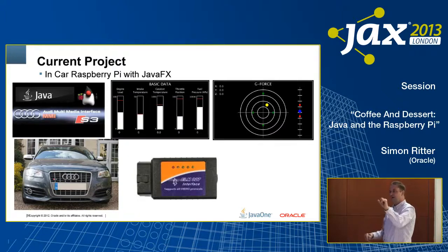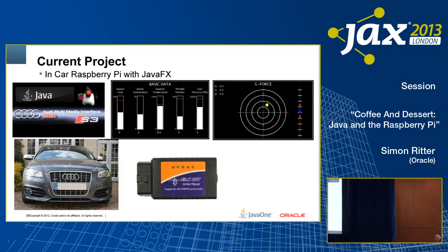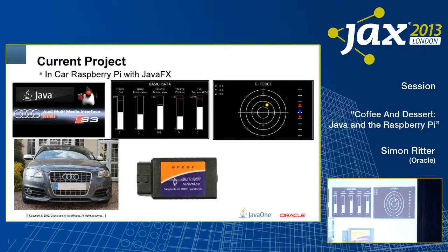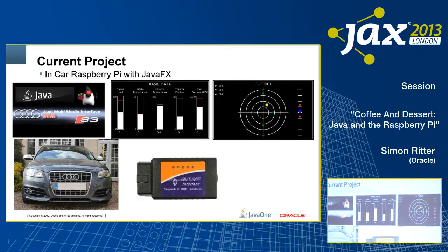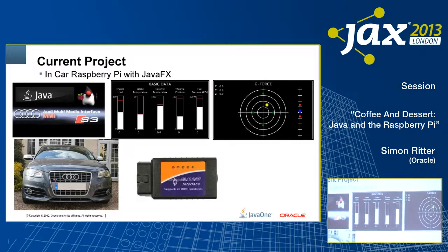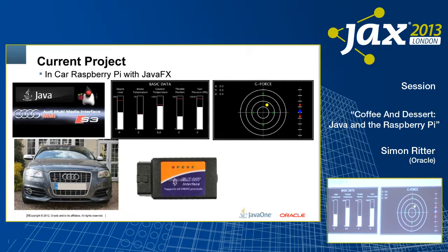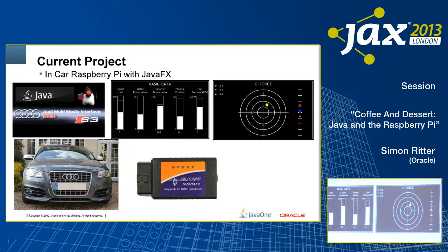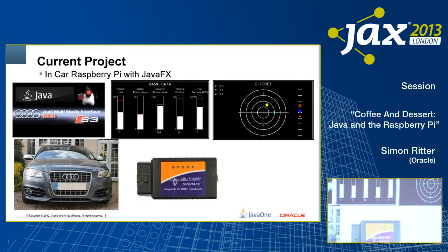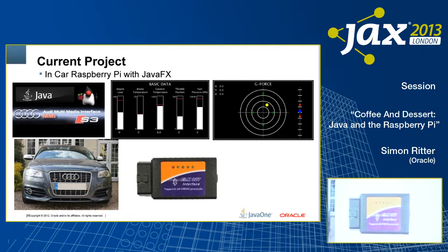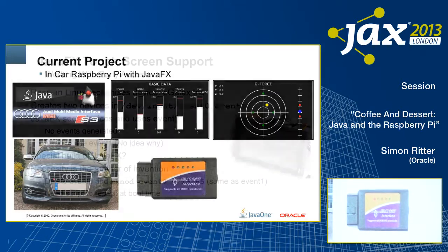So what I ended up building here was an interface which had a touch screen which sat on top of the dashboard, and then that would allow you to display different values you can see there. And I also had in there an accelerometer which I connected to the Raspberry Pi. So I could measure the acceleration of the car, take the information from the internal workings of the car, and then you could create values like the torque and the horsepower as the car's actually running. So that was kind of interesting to do.